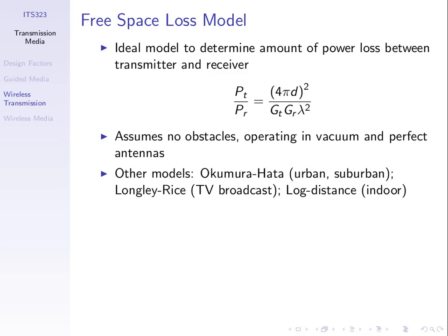In real life, there are obstacles, there is noise, we don't have perfect antennas, perfect devices. There are other models that people have developed to model how much power we lose in different scenarios, for example inside a city, or for TV transmission across a city, or inside a building.